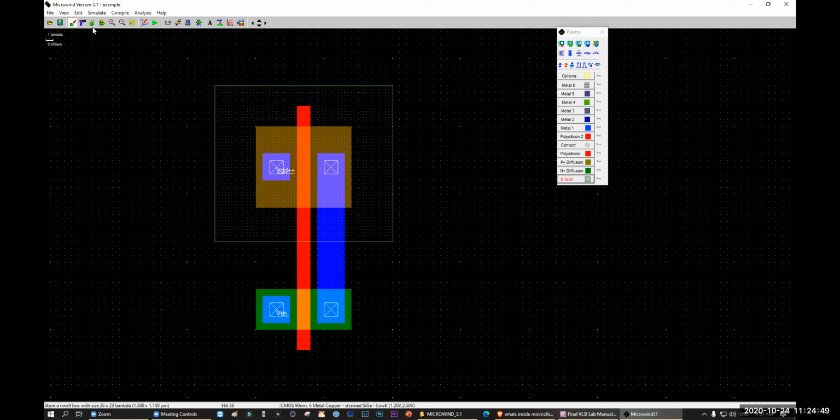So how can I do that? Click this button, move or stretch. Click it. Which one is small? This one is 6, this one is 6, this one is 6, right? Which one is not 6? The bottom one is not 6. Yes. So I'm going to click the bottom boundary. Click it. Okay? This is called correction. Understood? Yes, sir. This is the N-well.